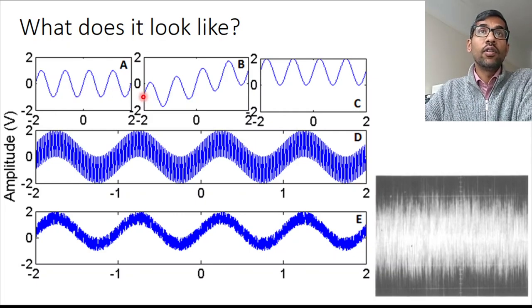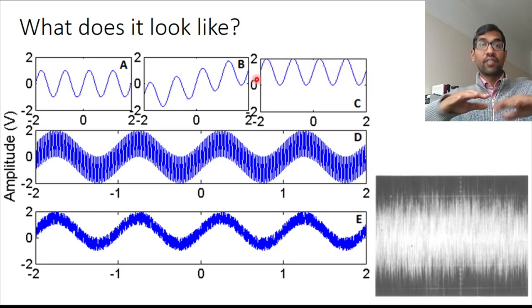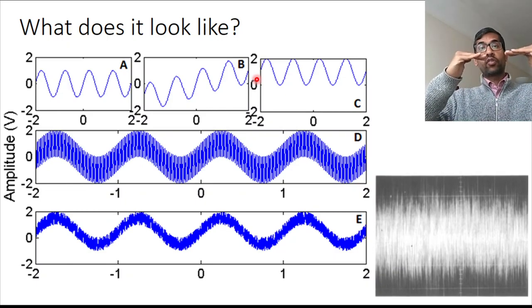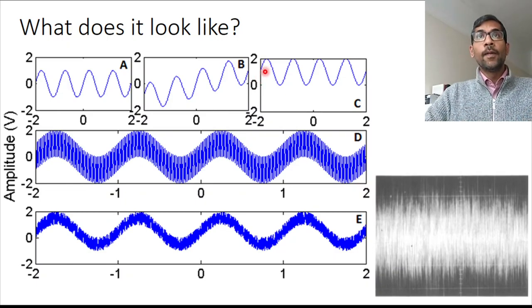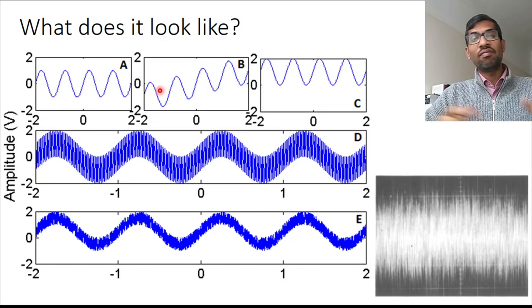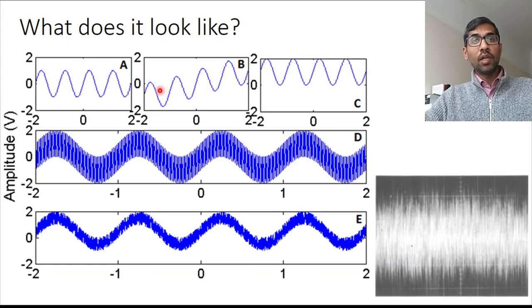This noise here is just an offset noise. Instead of the signal being at zero, you have the offset added to it. But this offset sometimes may not be constant. It may be increasing, like in this case. Then you could call it variable offset, but you could also call it drift.